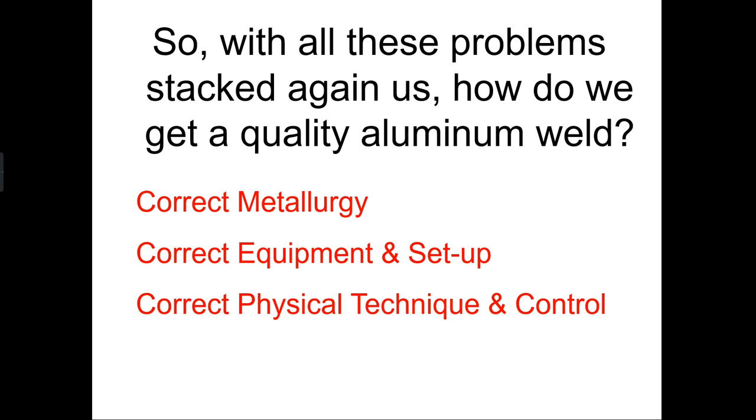Physical technique and control is probably the biggest challenge when it comes to this, because we have to teach a hand what to do about location. We have to teach a hand what to do for the heat control, the current control that's going to be right on the torch. And we have, of course, a piece of filler material in the other hand. So this other hand is going to be deciding when to put that filler material into the puddle, and that takes a little bit of practice.